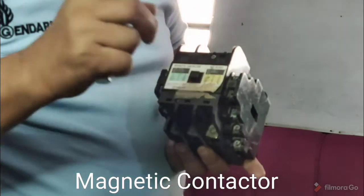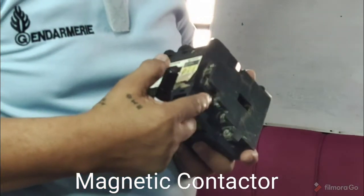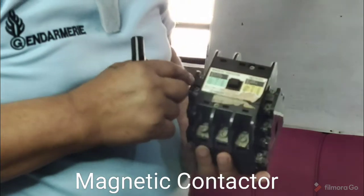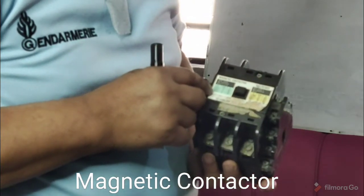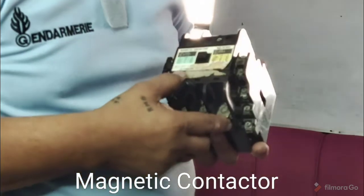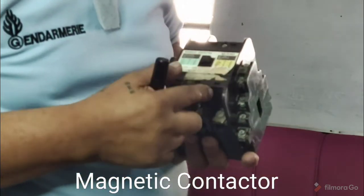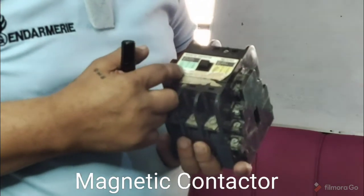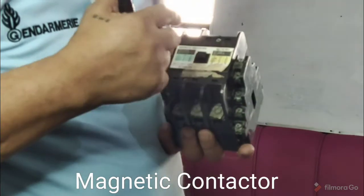Now, considering that the holding coil or the magnetic coil here is 220, I said this can also be used for 440, 550, meaning the contacts are capable for 220, 440, and 550. Now, the holding coil is 220.